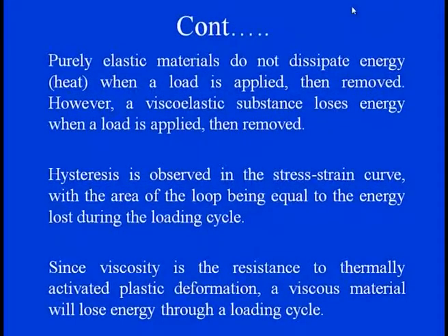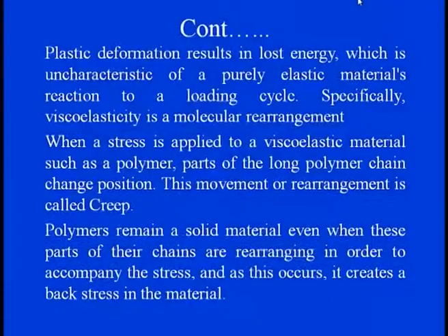So hysteresis is clearly observed in the stress-strain curve, and this area gives the amount of energy lost. Since viscosity is the resistance to thermally activated plastic deformation, a viscous material will always lose energy in every loading cycle, and this plastic deformation results in the loss of energy.